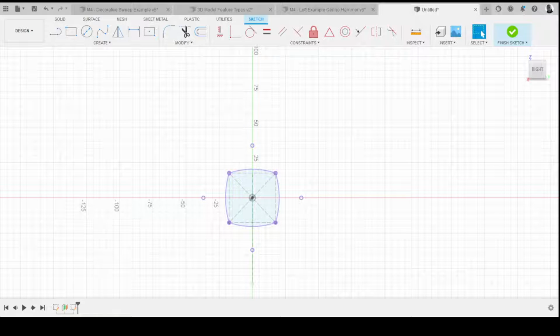So now we've got another sketch which is exactly the same size as our previous one, but we want to make this one a bit bigger. So what are we going to do for that? The one we just projected is the purple one. Yes, any geometry that's that kind of pale purple has been projected. So we're going to create an offset by going up to modify, offset or O on the keyboard. It's another one you use all the time, so it's worth getting used to that.